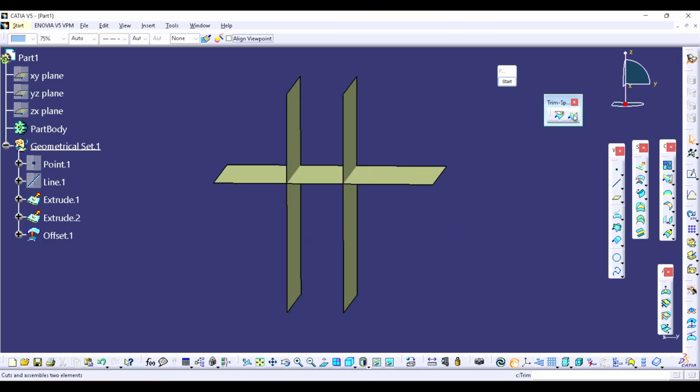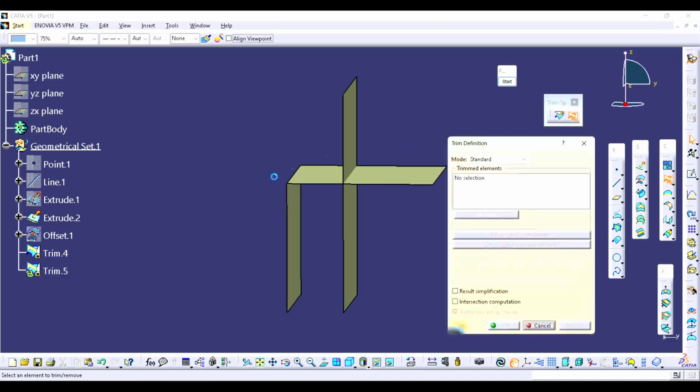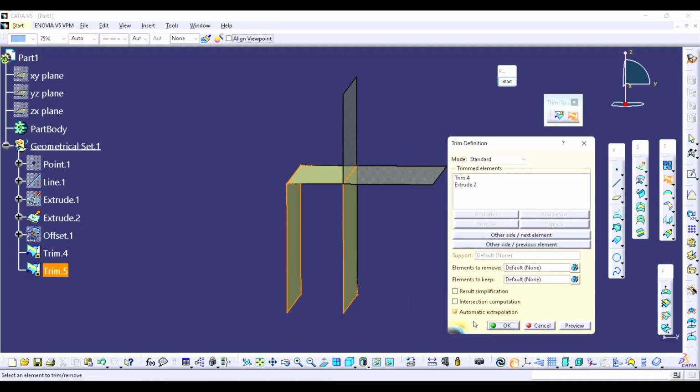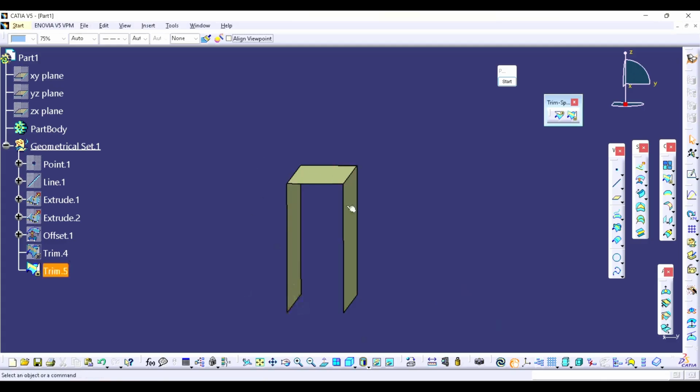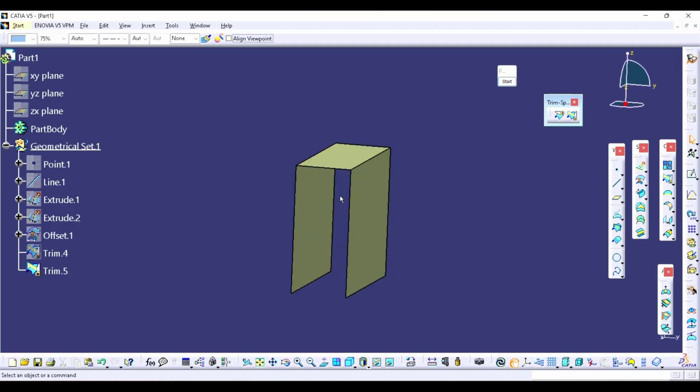Which one I teach? This first two surface in one trim, and then select the first trim and then the surface. Okay. Please refer this method if you want to create a full better parametric parts, and it will be easy to modify for your colleague also, because you're going to work in a teamwork. Okay. So I will teach this for the surfaces, but you can use the trim for the curve also. Let me show you how this will work.